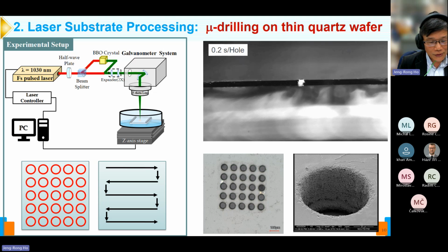The machining challenges include that we have to preserve single crystal structure without amorphous and twin crystalline defects around the surface of the holes. And we need to avoid any potential micro cracks and also achieve very low roughness, sometimes needed below 0.5 Ra, roughness less than 0.5 microns.